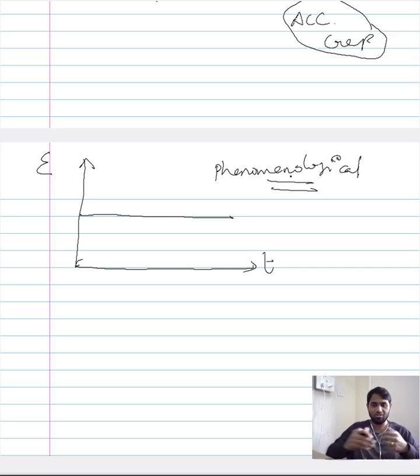It's just phenomenology, and this is the approach that we take to study the creep curve. This is one of the easiest ways of studying the creep curve, and also of theorizing, or postulating something. So instead of analyzing the creep curve as a whole, or getting a theoretical understanding of the overall creep curve, you are sectioning it and considering the theoretical reason for each of the sections and then combining it, not to give a prediction, which we assumed in the previous lecture, but to get a holistic understanding of the creep behavior. That approach is referred to as the phenomenological approach.